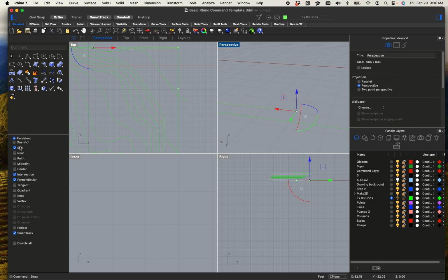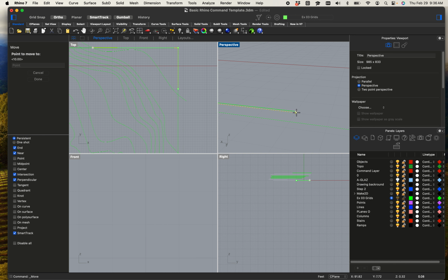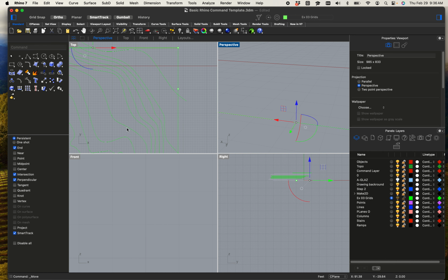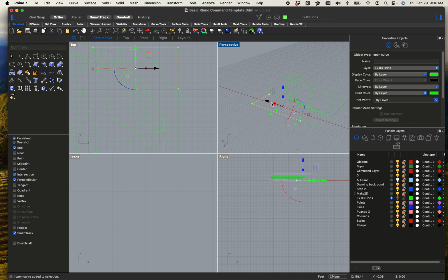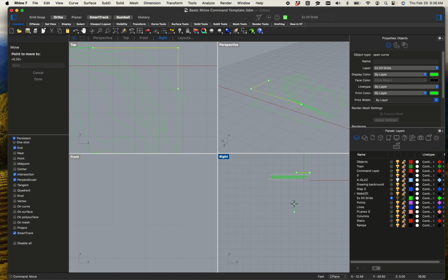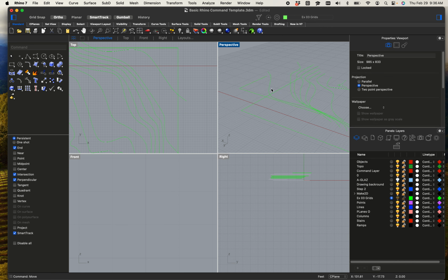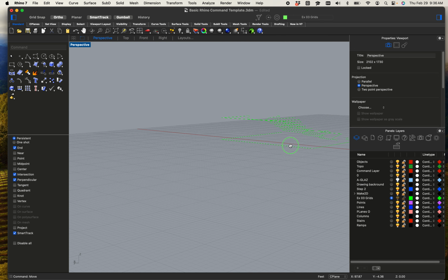And this is where near actually does come in handy. So I'm going to go ahead and move that particular point and get it perpendicular or near. Right? Turns out perpendicular was just fine, but very easy in making that flat. I could have used Make 2D as well, but I need to move this, and I'll show you why. 10 feet, right? Because we kind of have to complete the rest of the surface. Unfortunately, the program has no idea what we're doing. We're just using it for the tools of visualization that it does have, right?